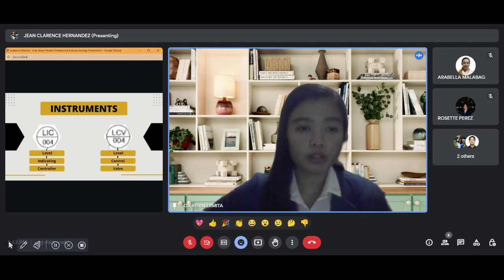Next is the level control valve, and the purpose of this in a glycol dehydration process is to regulate glycol circulation, ensuring precise control over liquid levels in both the absorption and the regeneration phases. By facilitating controlled glycol flow, the valve contributes significantly to the efficiency, safety, and reliability of the glycol dehydration system, ultimately influencing the quality of the treated natural gas.